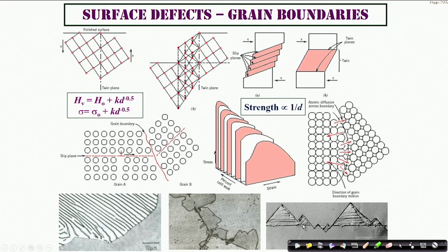The boundaries can take very typical shapes, where it could be non-faceted or curved, or it can take a shape which is very geometric and flat. Such flat and geometric boundaries arise for one set of crystals under one set of conditions, whereas such curved boundaries can appear in other kinds of crystals. And the reason why the shapes are different is principally attributed to the surface energy, or interfacial energy, associated with them, which is in turn related to the crystals and crystal structure that we are dealing with.